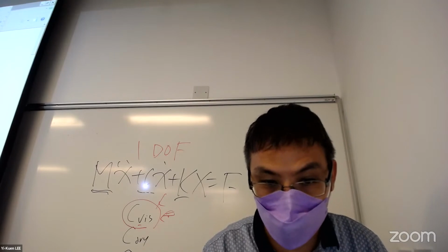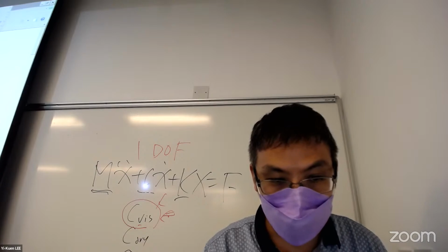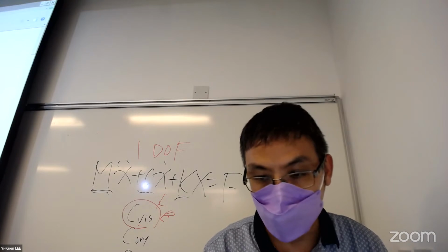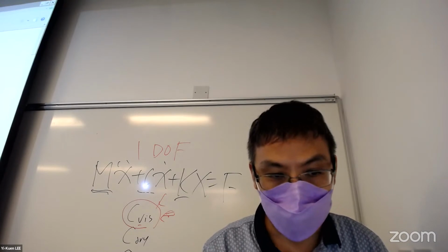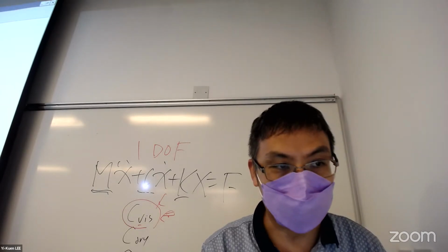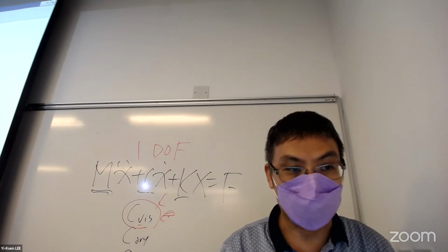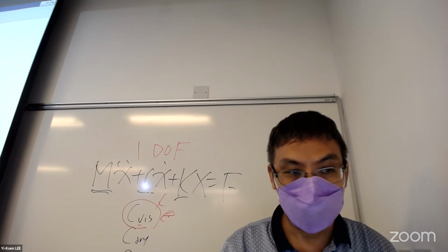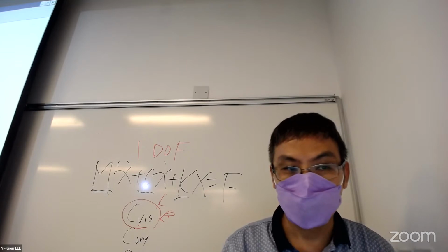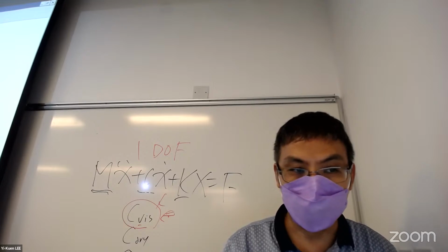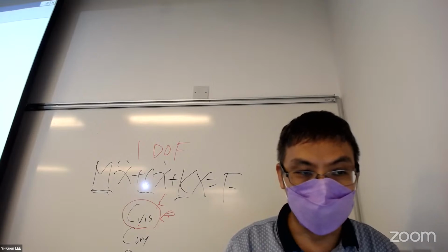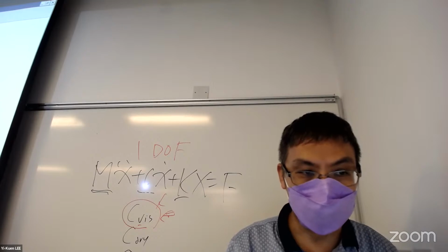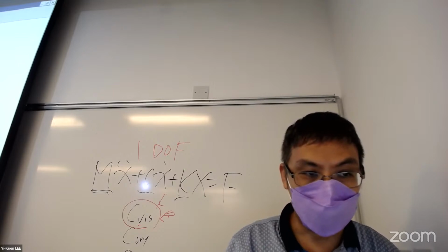From my point of view, both this kind of analysis and demonstration have their own value for real application. Let me quickly show you how we can produce this kind of response. Basically, you need to define the natural frequency, maybe omega n, or we define R. R is the normalized frequency. For example, you define omega from 0.1, with a step of 0.01, to maybe 10, and then we look at R equals omega divided by omega n, normalized here.